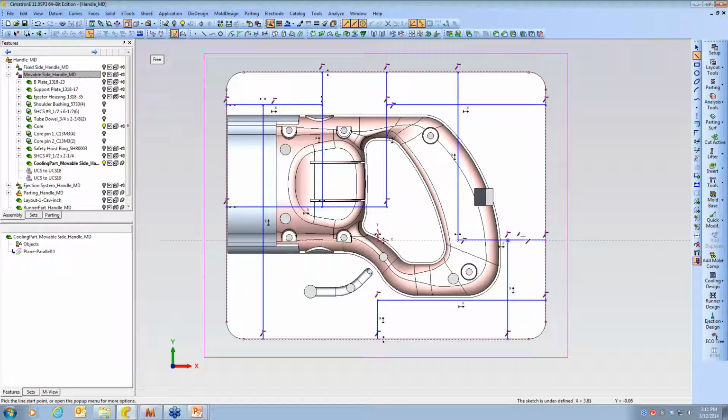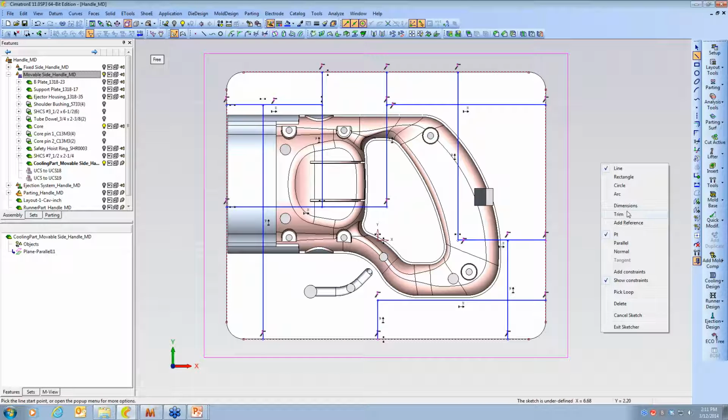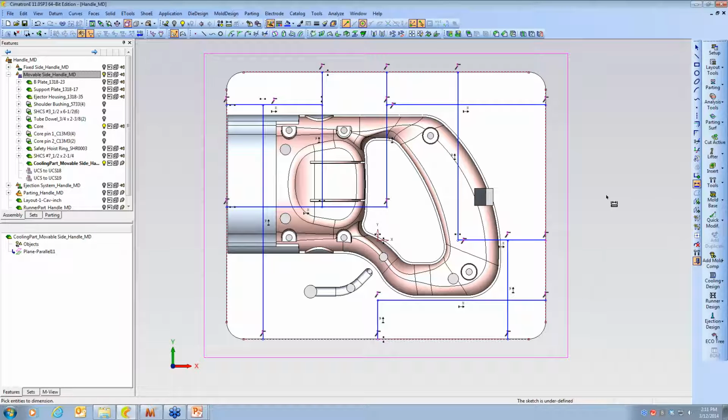It is possible to make calculations involving the heat content of the plastic being introduced and the many factors involved in removing that heat. But most cooling circuits are designed using good rules of thumb and practical experience. So bending the circuit around contributes to turbulent water flow, which is a good thing for pulling the most heat from the steel. We only need to be careful not to make the circuit too long or too complex. It's generally agreed that the water should be kept moving and that the water exit temperature only be around 10 degrees hotter than what's coming in.